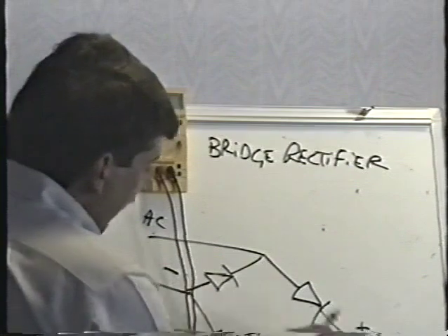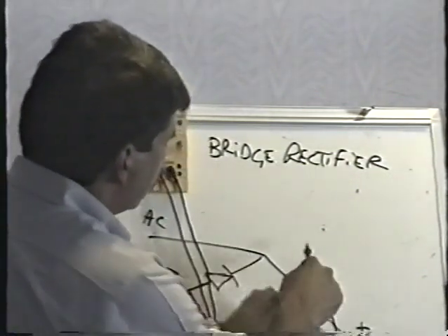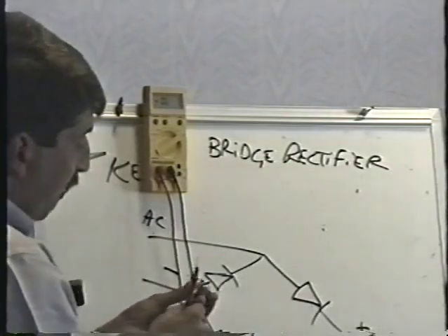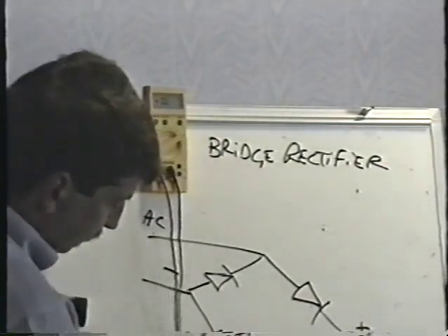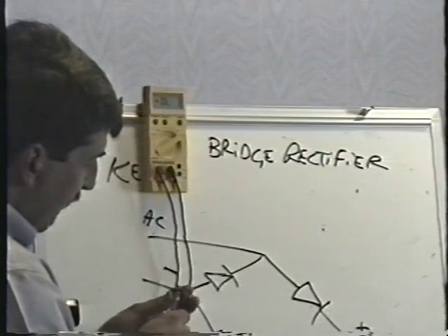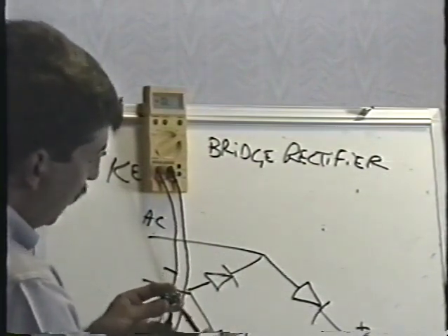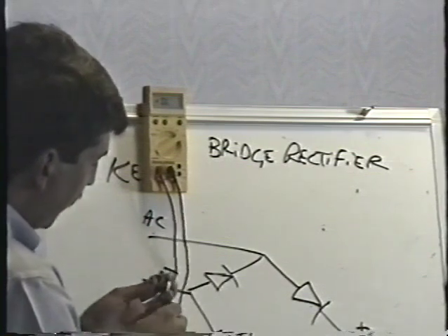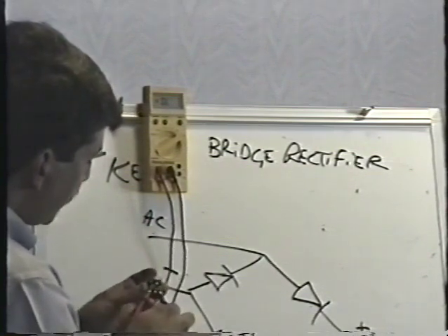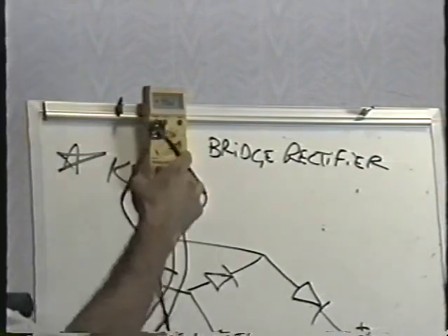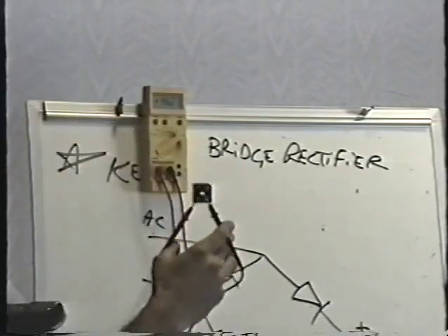What I'm going to do is check each of the 4 diodes. If any one's bad, we'll know it in a hurry. So, you can really start anywhere. It doesn't matter. Start with any lead anywhere across any diode, and I get an open reading in that direction. When I reverse the leads, I get a junction drop. Now in this case, the meter only says 0.462.